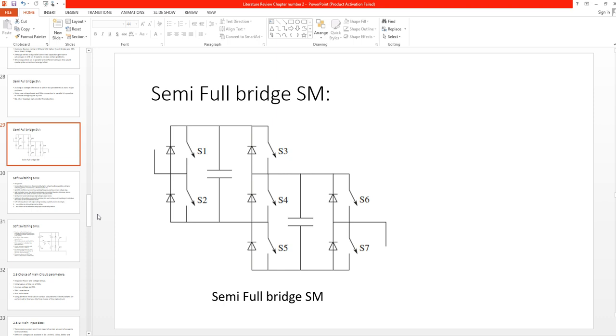We require a very low switching frequency, and our concern is that the voltage drop must be very low whenever the switch turns on. Too much effort is made to increase the switching speed, but too little effort is spent on achieving minimum conduction losses. Minimum conduction losses are the most important in MMC. We don't want the conduction losses to be very high because our switching frequency is very low, and we are not interested in higher switching frequencies.